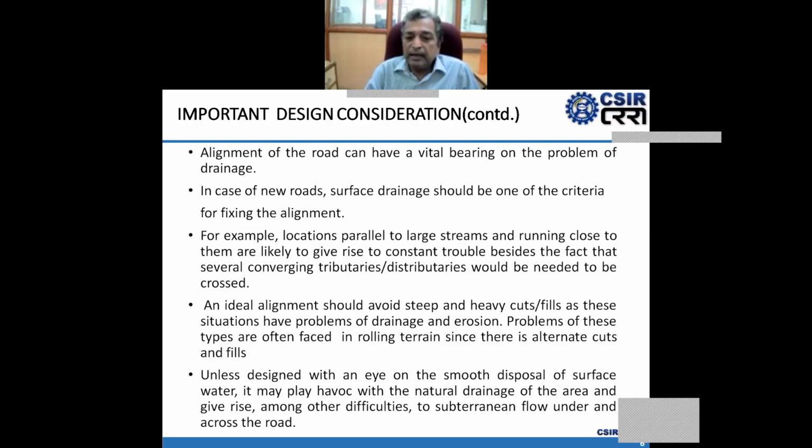For an ideal alignment, avoid wide, steep, heavy cuts or fills, as this situation has problems of drainage and erosion. Problems of these types are often faced in rolling terrain, since there are alternate cuts and fills.